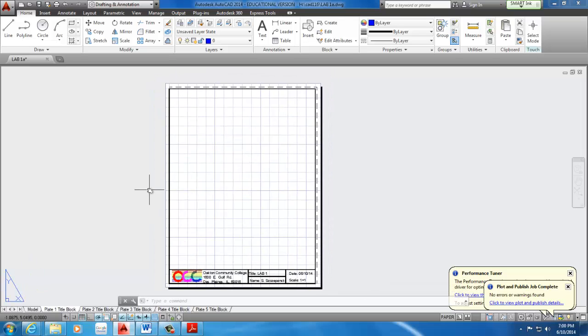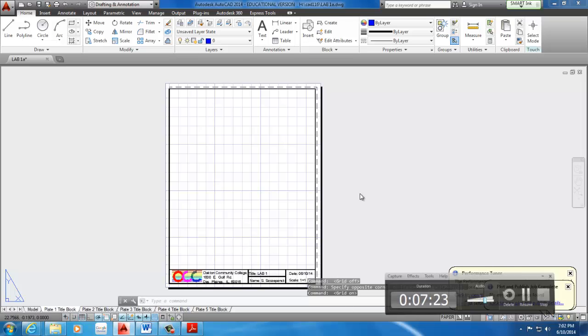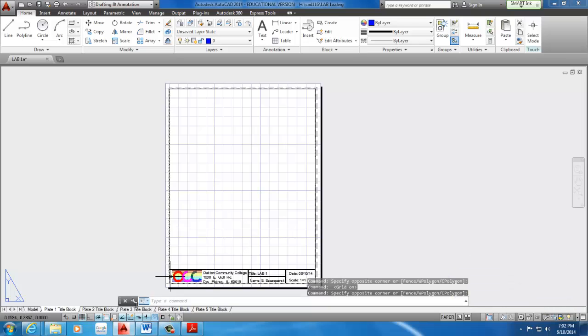And what we're going to work with is using the grid system. That's our basic understanding of AutoCAD, very simple and easy. To do that, you have to activate, there's a tab on the bottom here that says, okay, so hopefully your file has the grid on. It's pretty pre-established. So grid display is on. You can even type in F7. If it's highlighted right down here, that means it's on. If it's not, it'll be gray, which would mean it's off.